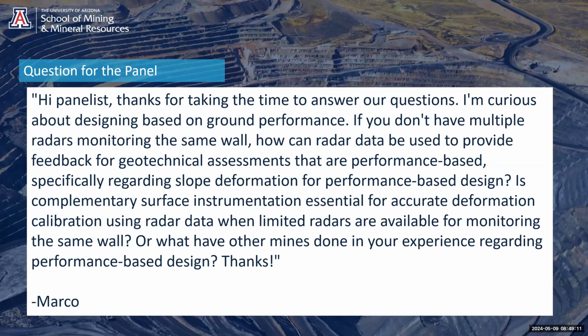So radars don't give you an absolute metric of displacement. Those are better obtained through other techniques, including the real vectors of movement. Radars only give you one component. If you have three radars pointing at the same slope, which is quite expensive to do but is doable, then you could have vectors of movement from the radars.